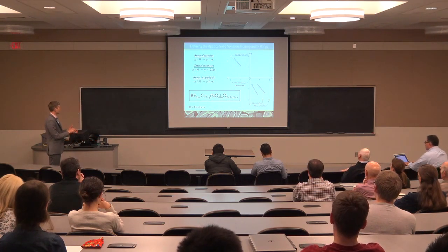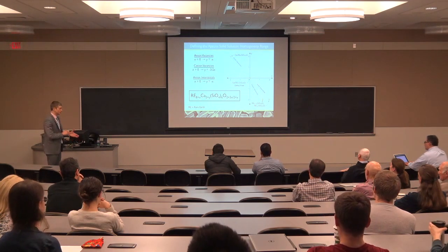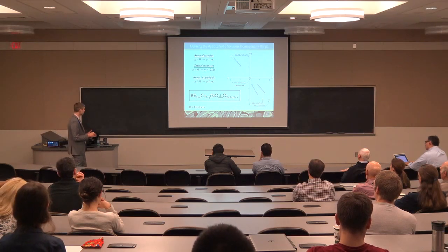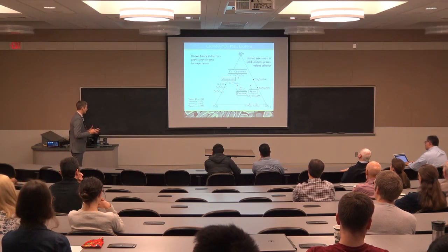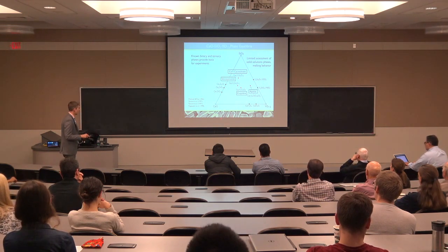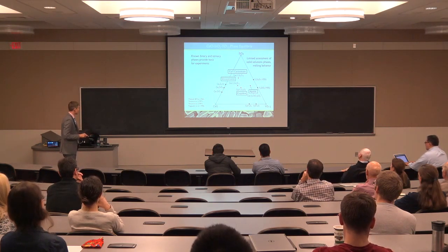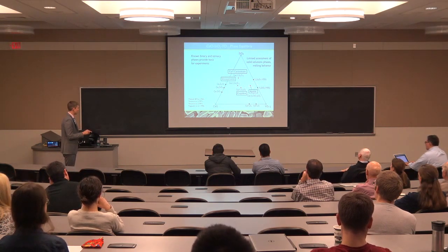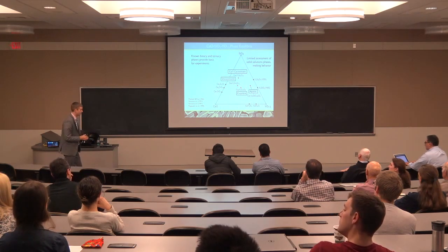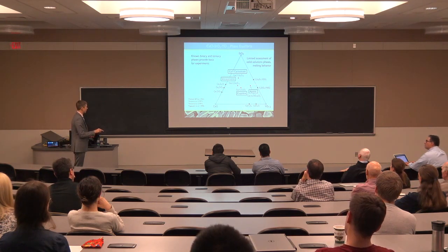And then the question is, if this is the allowable range based on an understanding of the crystallography, what is the actual stable range relative to competition to crystallize other phases? And so to do that, we need to then consider the phase equilibria in the broader system. And one of the important systems ends up being the silicate calcium rare earth system. Apatite sits here. In this case, there were a variety of other ternary phases that had been suggested in the literature. But what we were after really is what is the stability range of apatite?